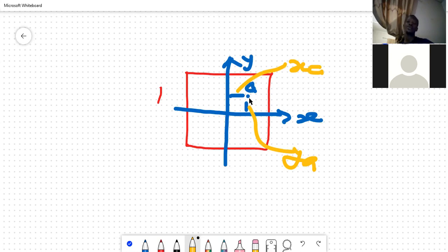All right, and so we can now measure along that. And then the y is a distance parallel to the y-axis, and we measure along that to meet the point of interest, with the x being a reference. So we measure the x coordinate with the y as reference, because these two axes represent the origin of the coordinate system. So 0, 0 becomes the center of the photograph, more or less, in a photo coordinate system, image coordinate system.